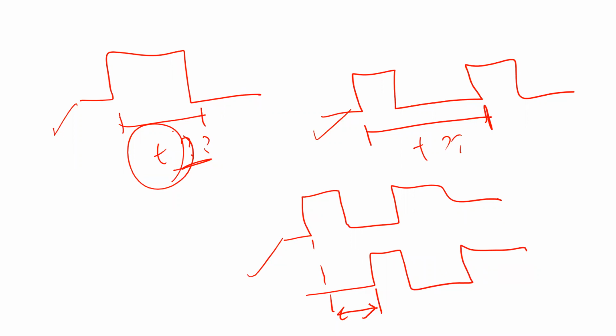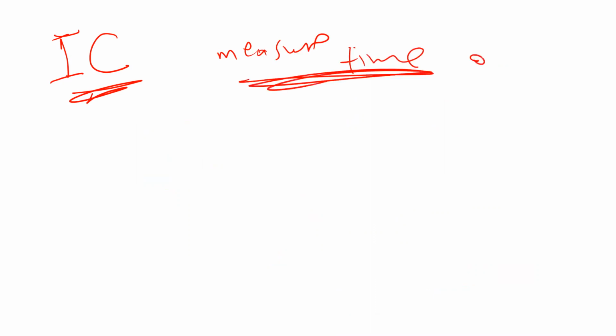The way you are going to do it is using input capture. I'm going to tell you how. Maybe you can use other ways, but input capture makes it very easy, very simple, okay? Input capture can only be used when you want to measure time, a period, a big period here. So every time there is an application where you want to measure a time for a signal this way, use input capture. This is why they made input capture. But how can this measure time? I'm going to tell you how as well.